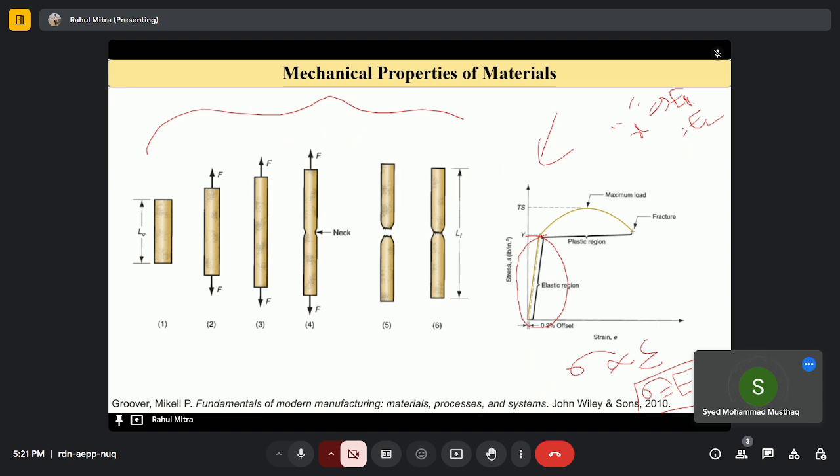So for that, the mechanical processes such as forming and machining succeed by developing forces that lead to deformation. Thus, the mechanical properties that are desirable to the designer, such as high strength, usually make the manufacturing of the product more difficult. It is helpful for the manufacturing engineer to design from the viewpoint of how the material can be used for the application.